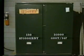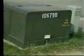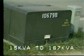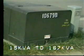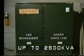Pad-mounted transformers are manufactured in both single-phase and 3-phase designs, and are applied to primary systems up to 34.5 kV. The single-phase units are built in sizes ranging from 15 to 167 kVA, while the three-phase transformers can be as large as 2,500 kVA.